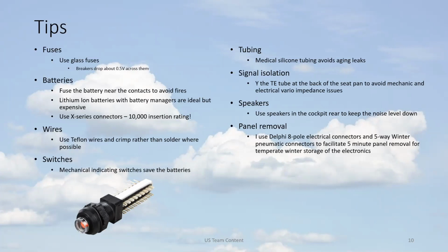The batteries, you really need to have fuses right within a couple of inches of the battery terminals to be safe and avoid fires, because just having them on the panel end, you could get a short somewhere and have the wiring catch fire between the battery boxes and the instrument panel, and that's a really bad day.